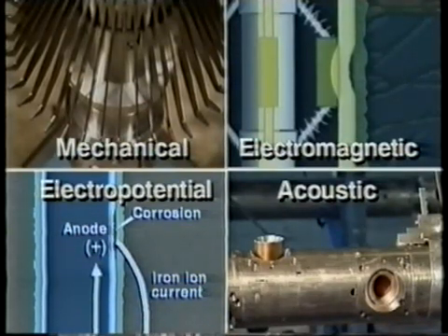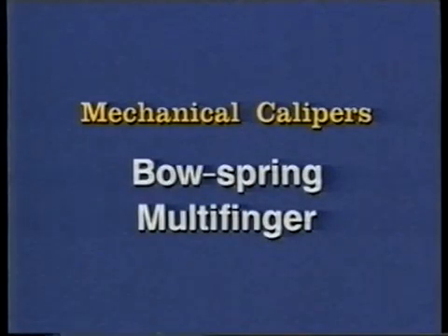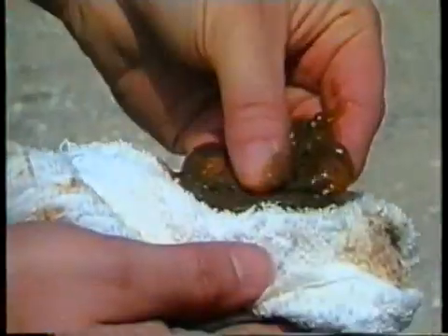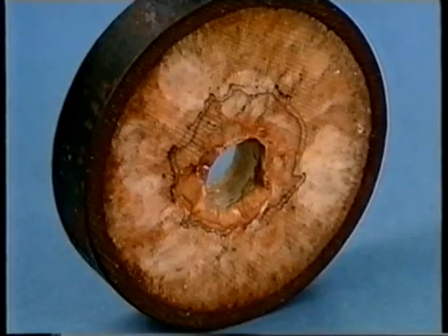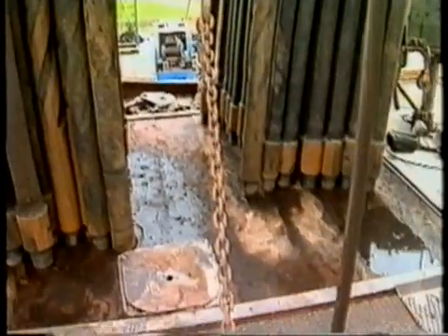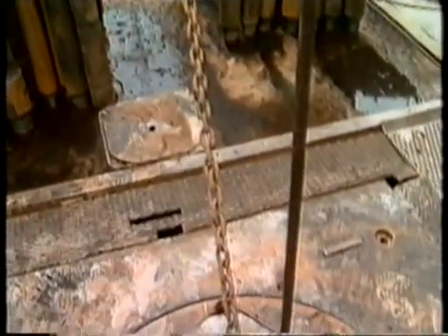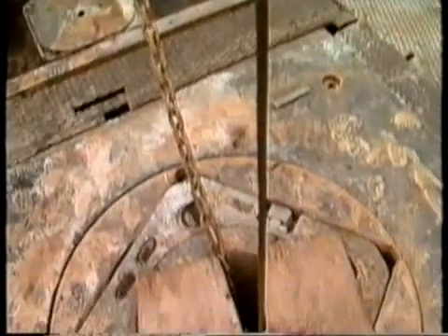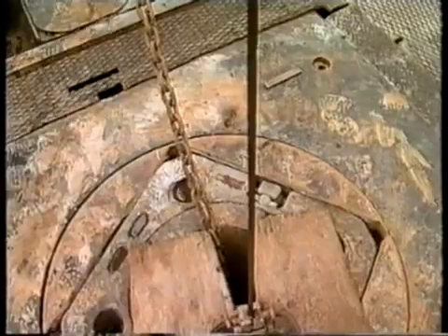The tools for these logs are through casing tools, not through tubing, and are generally sized to match the casing to be inspected. Mechanical calipers are of two basic types. The bowspring type caliper is typically run with a flow meter. It is often used to monitor chronic problems such as asphalt, paraffin, or scale buildup inside the casing. It is also routinely used in open-hole completions, where a flow profile using a flow meter is required.